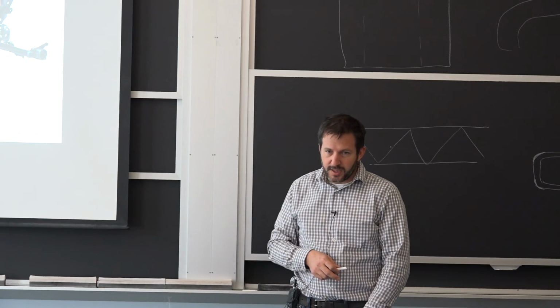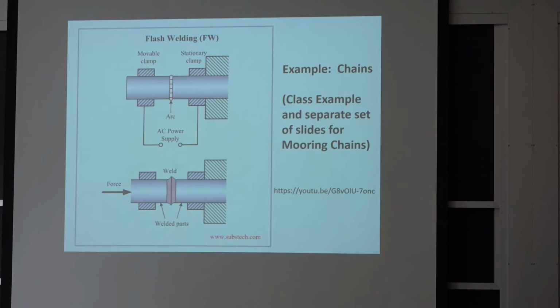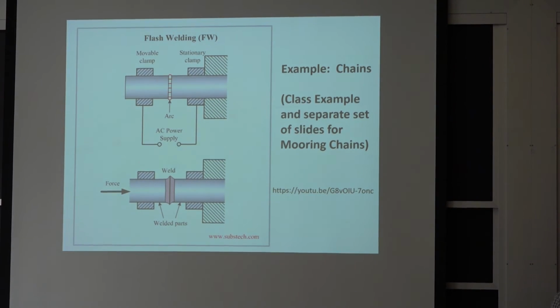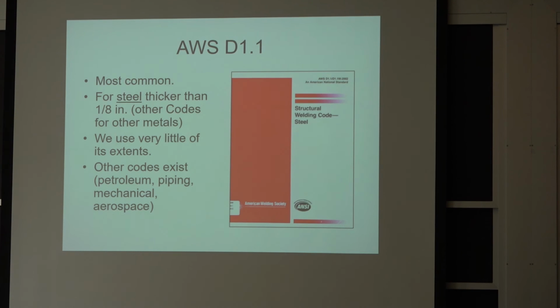So there's a very good reason for having those welding standards, I think you can see, because you can have so much variability. What the code says, and I'll go back to that slide, what this code tells you is if you have this type of steel, you can use this electrode, and it's going to give you these properties. It's very, very clear. If you don't know what kind of steel it is, you have to do enough testing to find an equivalent. And then you qualify your process that way.